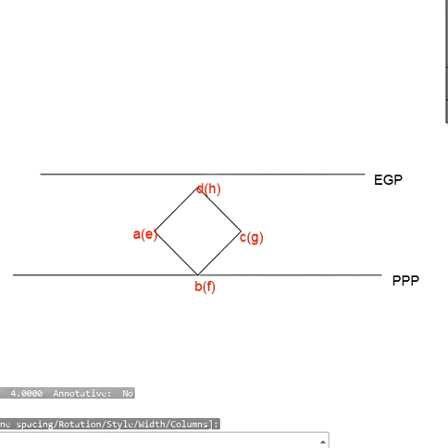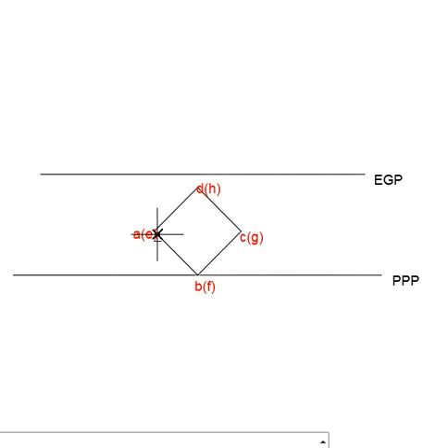Now you can draw the projection lines to get the position of all the points in the front view. So just draw the projection lines like this. In front view, the cube will appear like a rectangle. You can take the height of the cube. Height is 25, so from this point I am taking 25. So it will appear like a rectangle in front view.